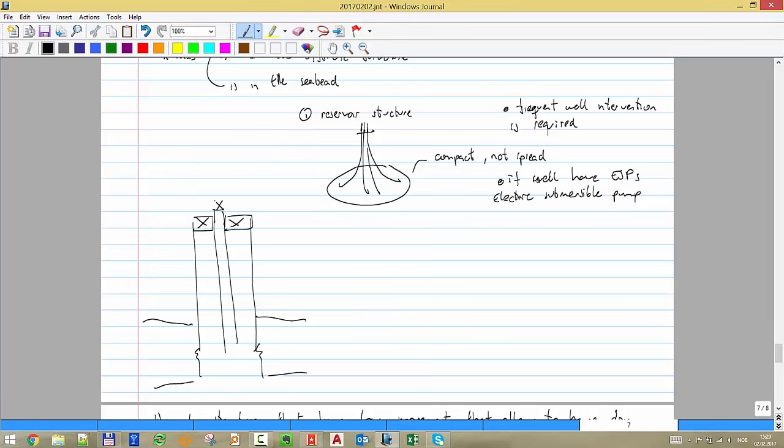So exactly here, we put a pump that is going to give a pressure boost to the fluid. Here I might have a very low bottom hole pressure that, if I leave it without the pump, won't be able to reach the surface. But when I add this pump, it boosts the pressure, and then I'm able to flow at that particular rate. The thing is that these pumps have a lifetime of maybe 1 to 5 years, and 5 years really only if you're lucky. We really say between 1 and 2 years.